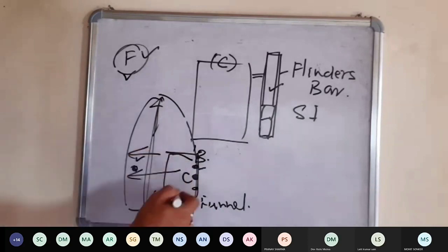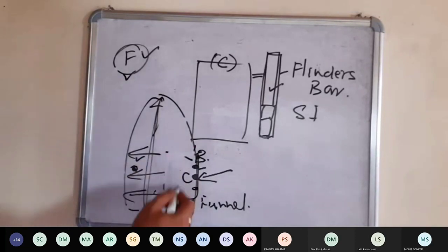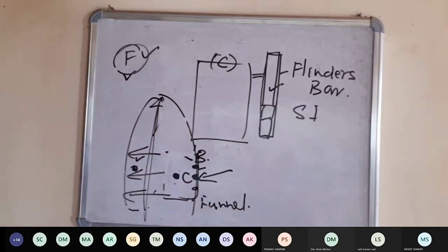So there is an asymmetrical soft iron in the athwartship direction. Effect of the starboard side will be more than the port. For that, we can also have a Flinders bar on the opposite side of the magnetic field. But that's not normally the case in merchant ships, which are normally made symmetrical, and the compass location is well balanced, so that the vertical soft iron on the starboard and port are balanced. The compass is in the center.